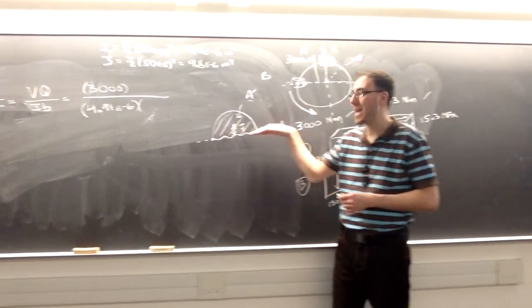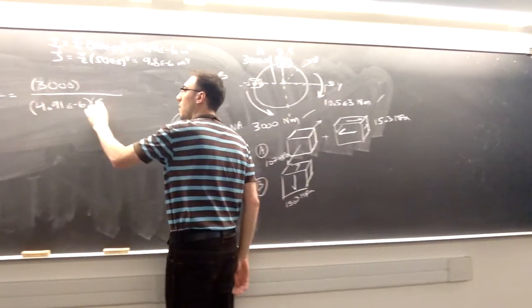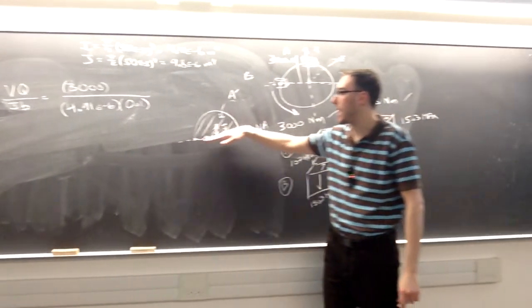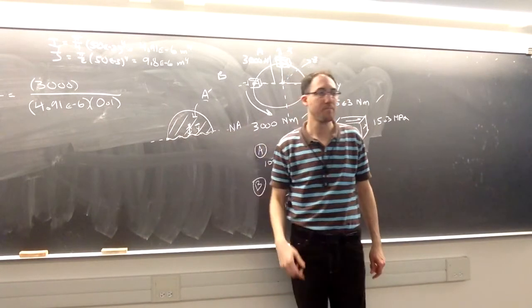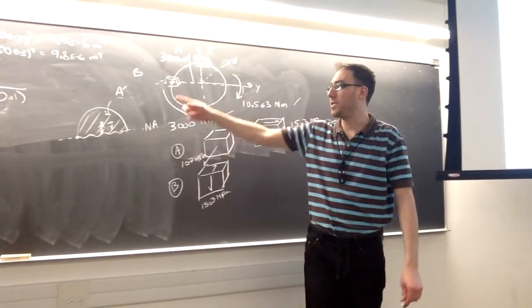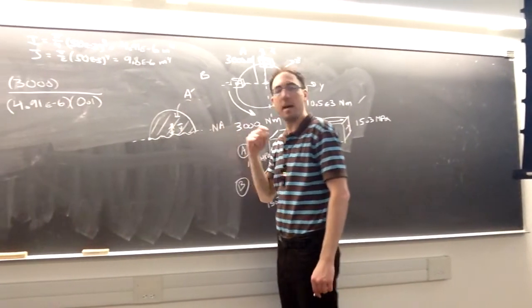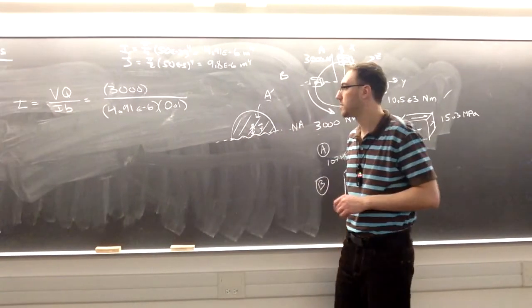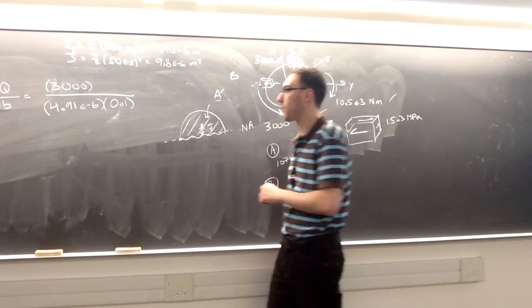We're cutting through the diameter, which we said was 100 millimeters, or 0.1 meter. So it's not the radius, it's the diameter. It's all the material we cut through to make this mini shape. And the value for Q in this case is going to be the area of our mini shape times the distance between the centroid of the mini shape and the neutral axis. So the area is just going to be 1/2 pi r squared.